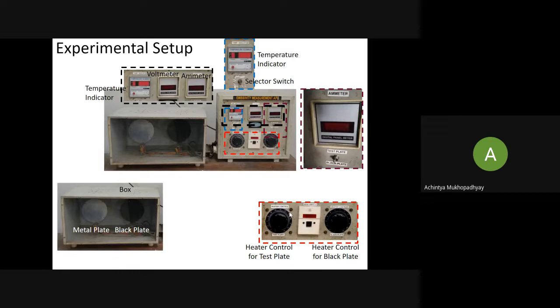So you put the setting at some watt, but that is not very accurate, and you do not use that value in your calculation. That is only for a kind of calibration purpose. So if you want to get the repeat reading at a particular condition, you should take the setting to a particular value. So that much will be ensured. But if it shows the value power to be say 10 watt, that does not necessarily mean that the actual power supplied is 10 watt. I mean, it is not a very accurate measurement. The voltmeter and ammeter readings are much more accurate.